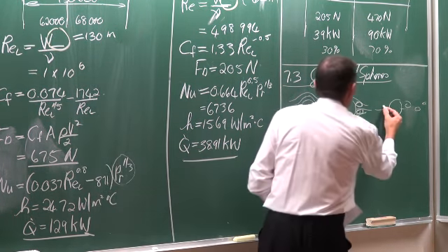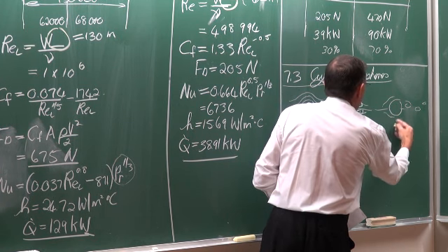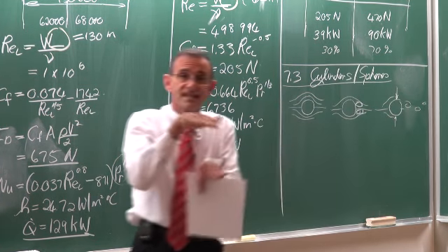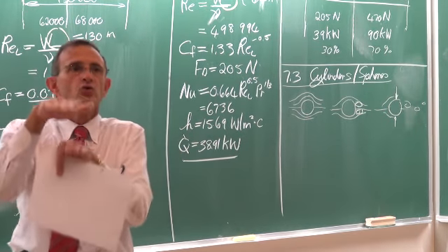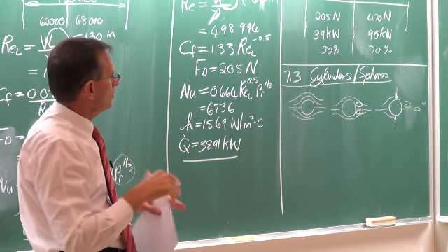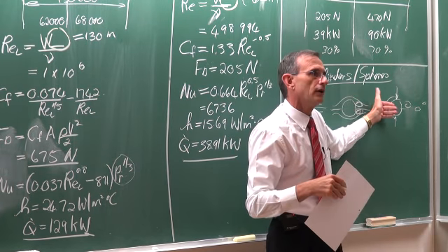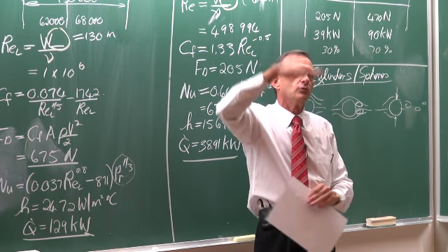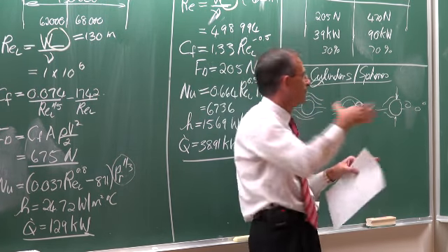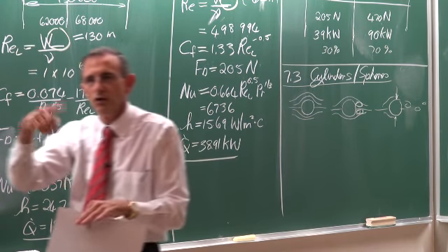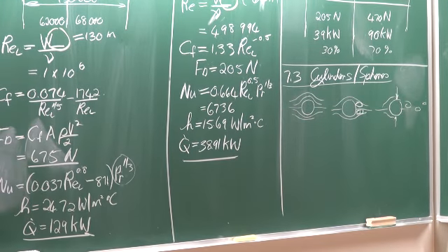Because of this, the pressures on this side and that side are not the same anymore, and that causes lift. If you would look at telephone lines with wind from the side, after a while it would start going up and down. It is because of the lift forces generated by the separation of the vortices at the back. So let me show you a video quickly.